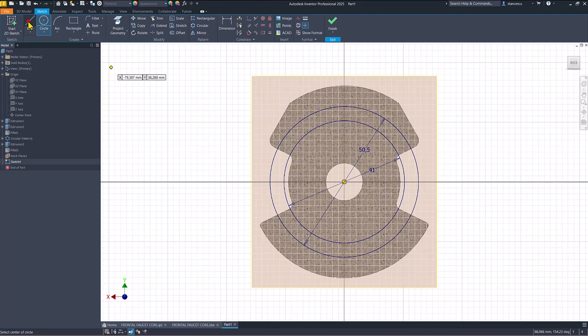Then we draw two small verticals. I place them specially not symmetrical, and now you know that they are not equal. I can make them equal to apply symmetry, my friends. Equal, and they are symmetrical. Take a look here. You see? The distance is 22.